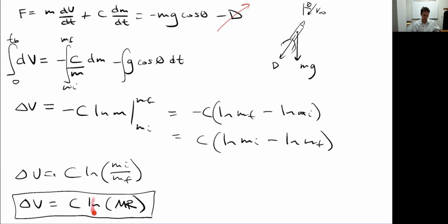A little further, right? This is actually kind of exponential. Notice it's a log term. If I solve this for the mass ratio I need, it's going to be this delta V over C. I'm going to have an exponential. So if delta V starts getting bigger and bigger, I just need tons of propellant, and that becomes impossible at some point. But, fortunately, once we get out of low Earth orbit, getting to other places is not nearly as difficult.